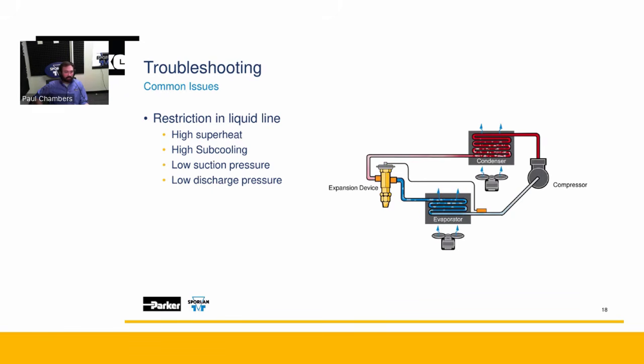Now, this is where these last 2 points, I have low suction. That makes sense. I'm dropping my pressure really low. Low discharge is one that can cause a little bit of question, because you'd say, well, if I'm stacking up all my refrigerant on the high side, wouldn't I see high discharge pressure? And it might depend on how the system is laid out, but you might actually see a low discharge, because all that compressor is designed to do on a lot of traditional systems is create a fixed pressure differential. You'll hear people refer to the envelope of the compressor, basically how it performs. And they'll be rated for a delta PSI. How much does it take from this to this?